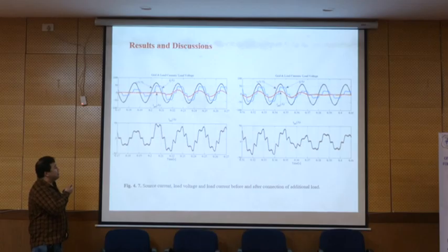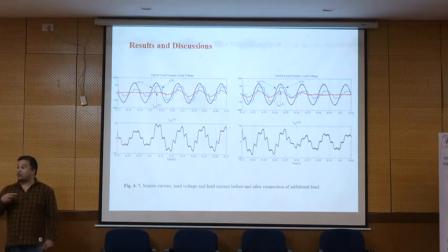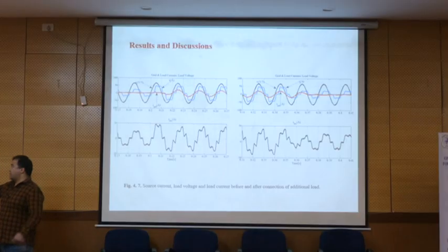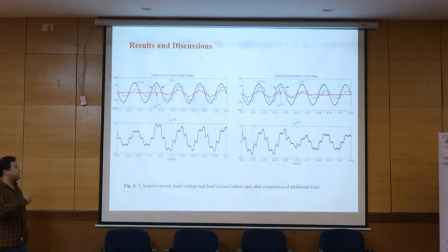Look, we are from 0.2 up to 0.22. Still we don't have too much power here because we are passing the transient time. And this transient time is the reaction of the PI controller. So it takes from 0.2 up to 0.22. That time we had the transient time, and then in steady state, we see that it's supported.